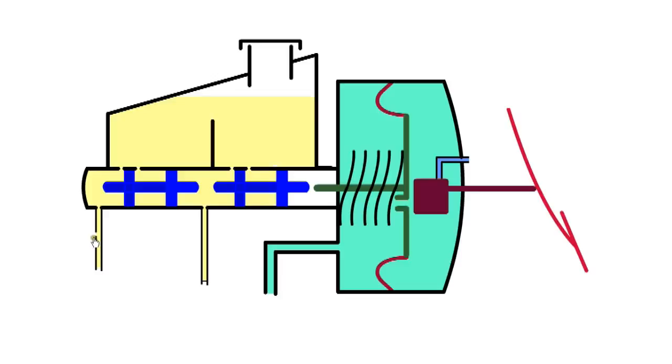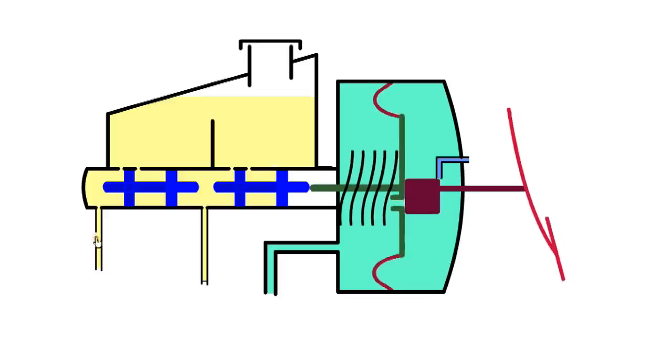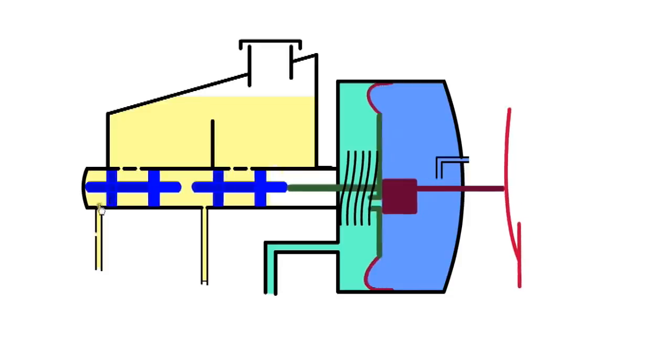If we have a leak in the left-hand circuit, its piston will move all the way to the left, as there is no restriction. The brake pedal will depress further, but will eventually build pressure in the other circuit. The division in the plastic storage tank ensures that if we have a leak in one circuit, we'll not lose all the fluid in the other circuit.